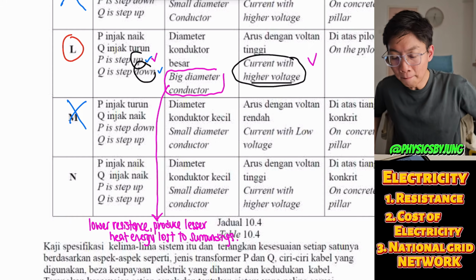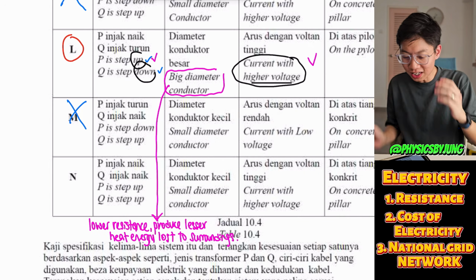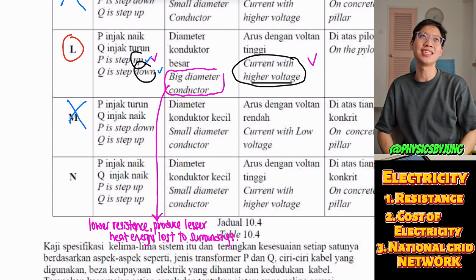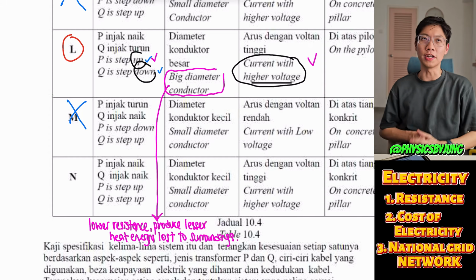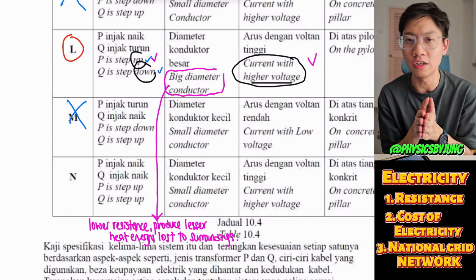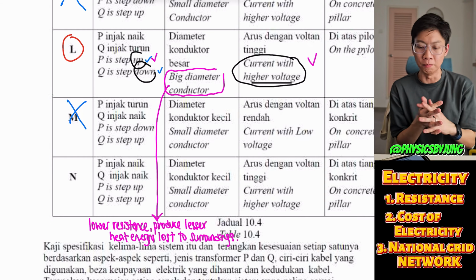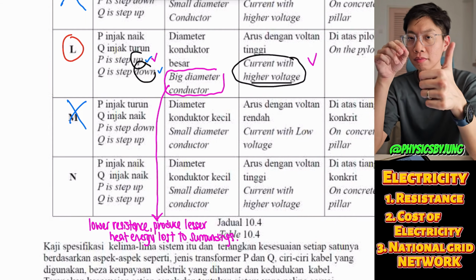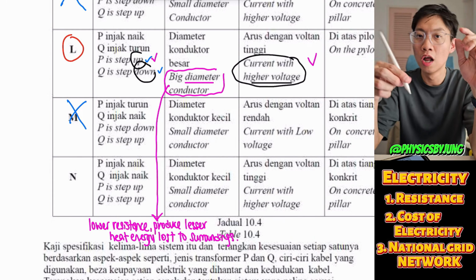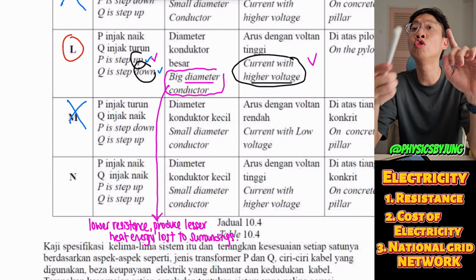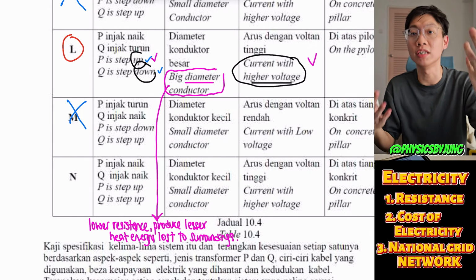Now please guys, I just want to urge you all: don't just straight away throw out an answer like "more efficient" or "higher efficiency". When you say something is efficient, you must explain why. For example, because a thicker wire, or a bigger diameter wire, has lower resistance, produces less heat, so it makes the system more efficient.